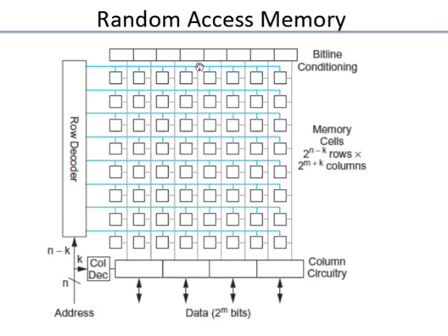When you activate one of them, what happens is the data in these square boxes, which are the memory cells, gets transferred onto these vertical lines, which are called the bit lines. So say this top row gets activated, that means that word line becomes active. The contents of each of these cells get transferred to the respective vertical lines, which are called the bit lines.